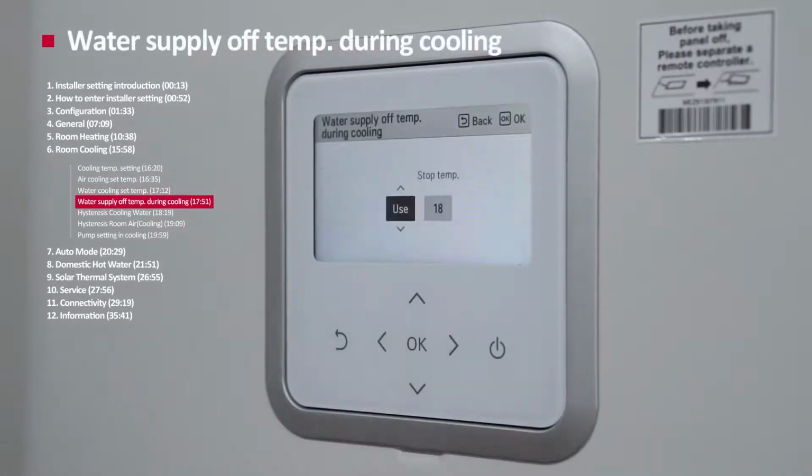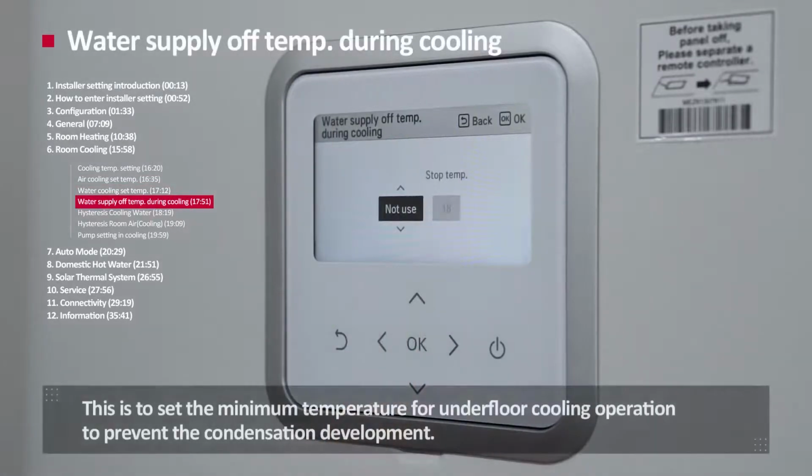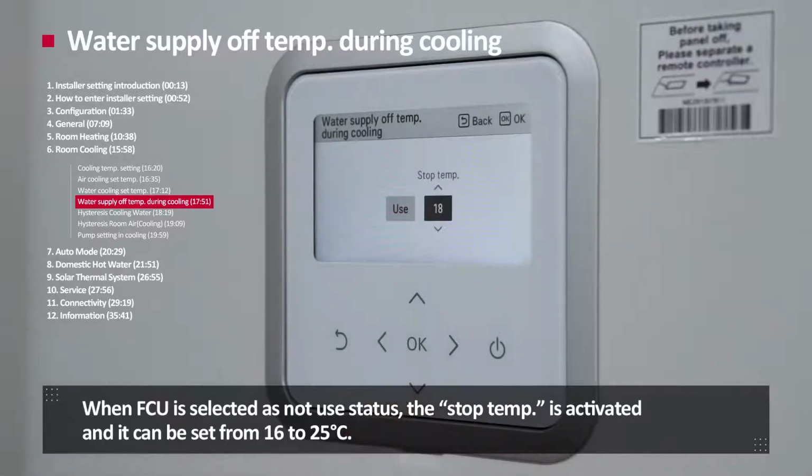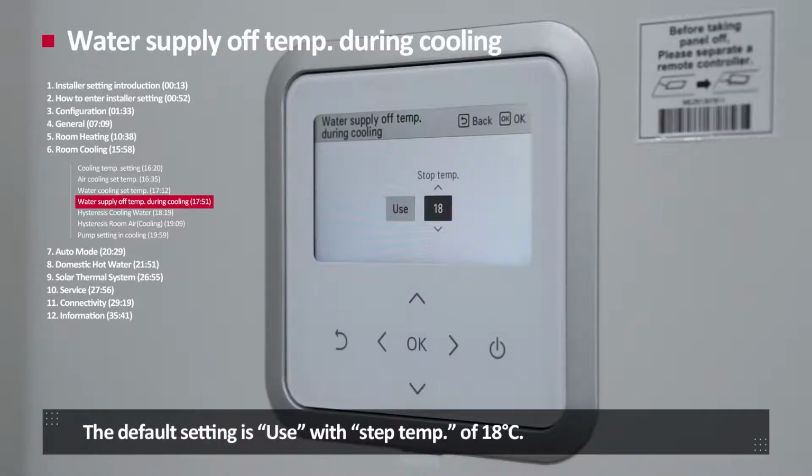Water supply off temperature during cooling. This is to set the minimum temperature for underfloor cooling operation to prevent the condensation development. When fan coil unit is selected as not used status, the stop temperature is activated, and it can be set from 16 to 25 degrees Celsius. The default setting is used with stop temperature of 18 degrees Celsius.